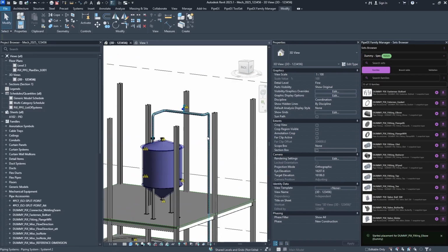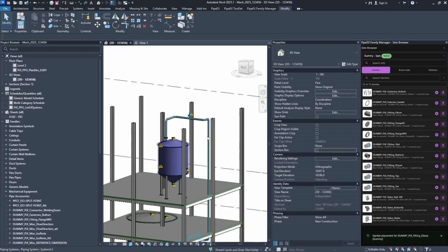You can select whole system by clicking on tab until you will see, in this corner, that you have selected the system, not component. So now you can see that you're pointing on the pipe type, then branch in pipe network, including branch objects, complete pipe network, and only now it's selected whole system.